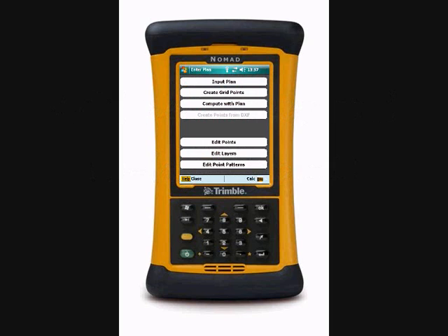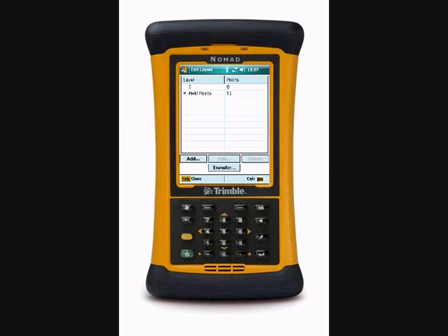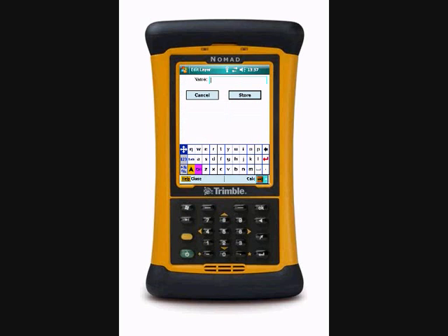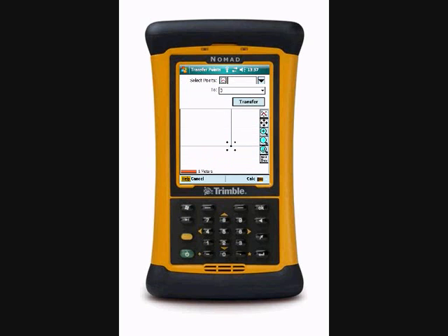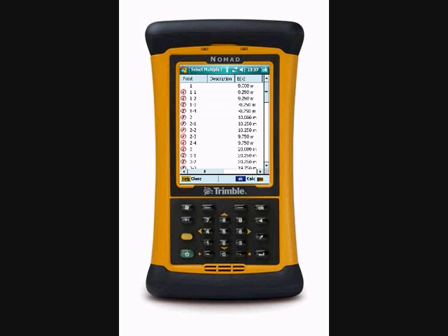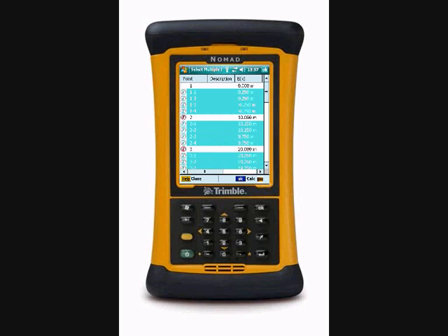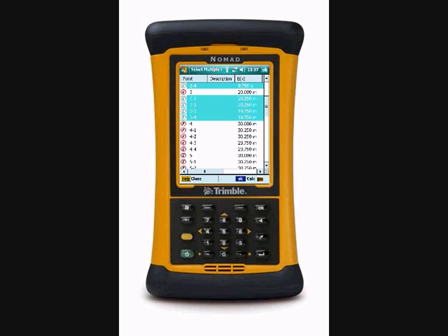What we can do is work with the layering as well to make our points easier to manage. I'll just create a new layer here for the bolts that we've just created. Just key it in here. Now what I can do is transfer the point patterns we've just added onto our new layer, and that gives us quite useful features in terms of managing the data visually, and we can manipulate that a bit more easily now. Very simply, this time selecting from the list rather than from the screen.